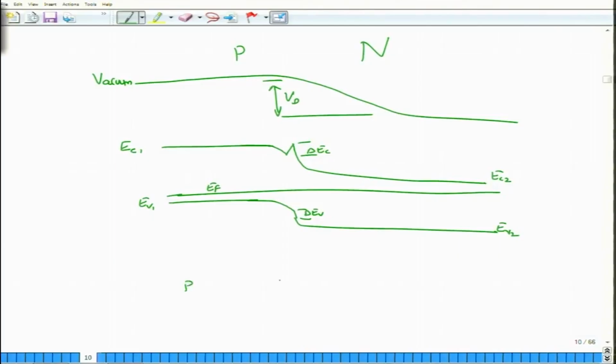but now if you put a P, an N and an N, right. So, you had created a P and an N and an N. So, there was a spike here, and you now know that if you were to follow it up with an N junction, so let us see if we can follow it up with an N junction, there has to be a spike, right. So, from the small N region it has to go down initially, then rise up and then fall down, well, exactly not, so this is the falling down. So, this is the triangular well that is created, this is the well that is created over here. Okay. So, these are the two wells created.